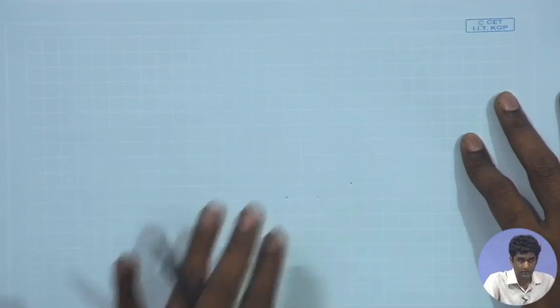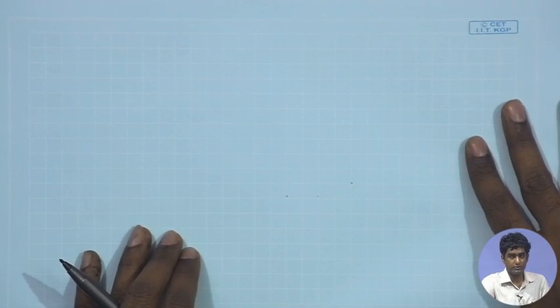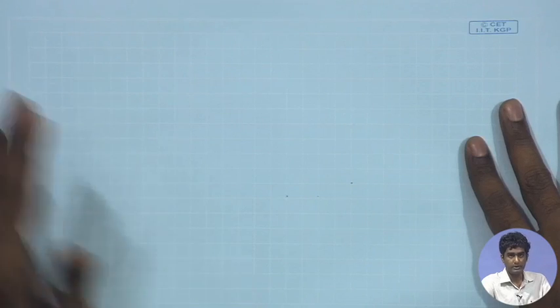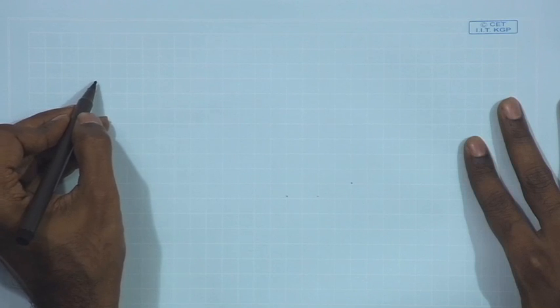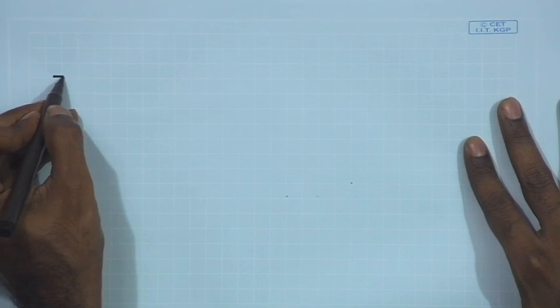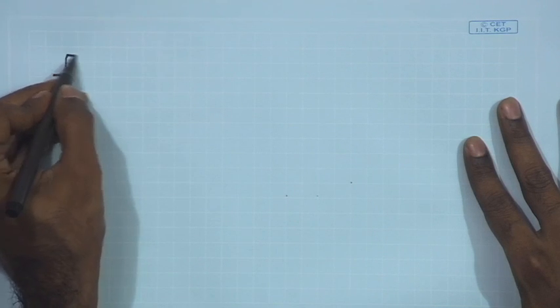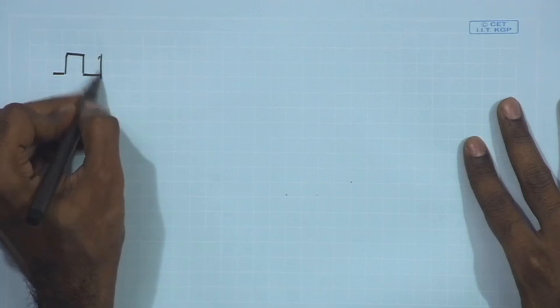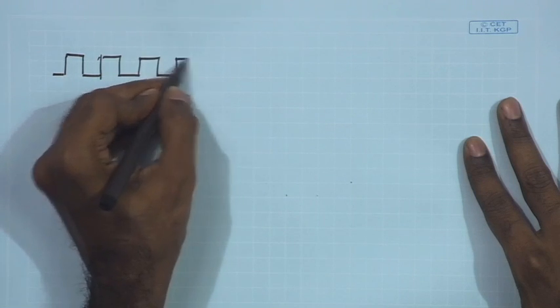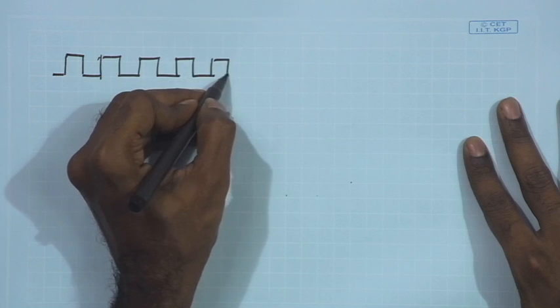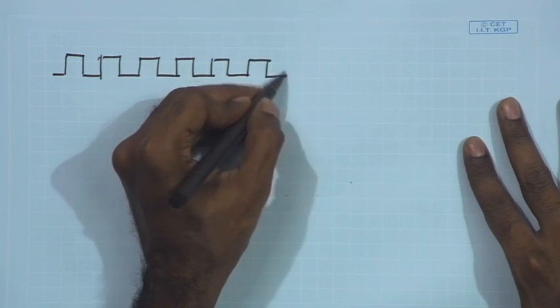So, we will revert back to our truth table for the counting operation and try to implement the overall scheme, where each of these flip flop stages in a chain is implementing the division of clock frequency. So, once again if I look at the clock waveform and try to see how these flip flops are going to be employed to construct the counting operation.